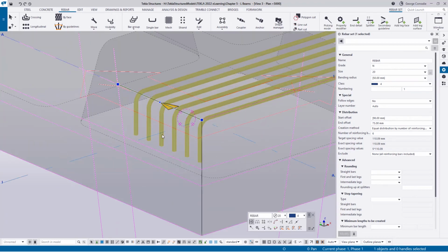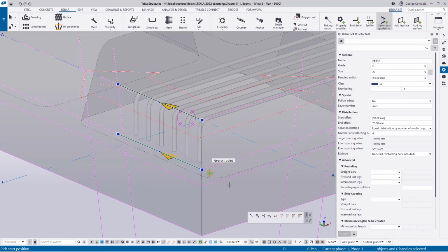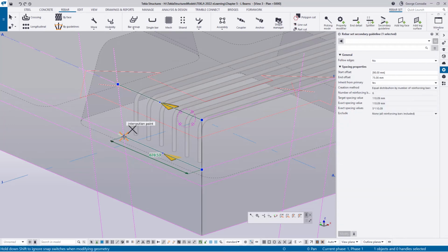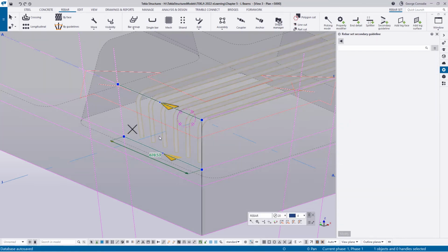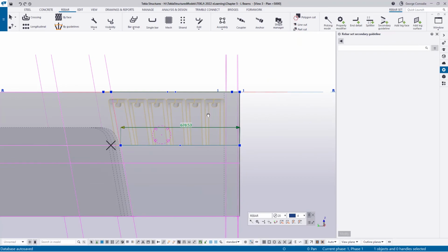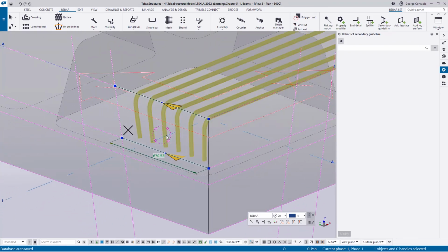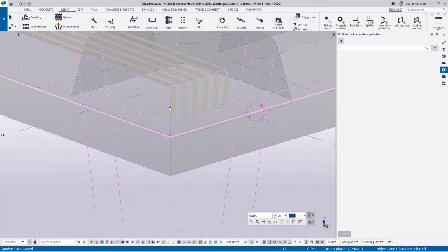You can just, when you click on this bar, go over there and say, give me a secondary line guide. And this time I want it from there. And because I was in that mode, it just sort of picked one. But what you can do is you can just hover over it, take this arrow and pull it back to that. Now, as soon as you do that, you can see how this curves in, like so. And it will automatically curve in the other side as well.